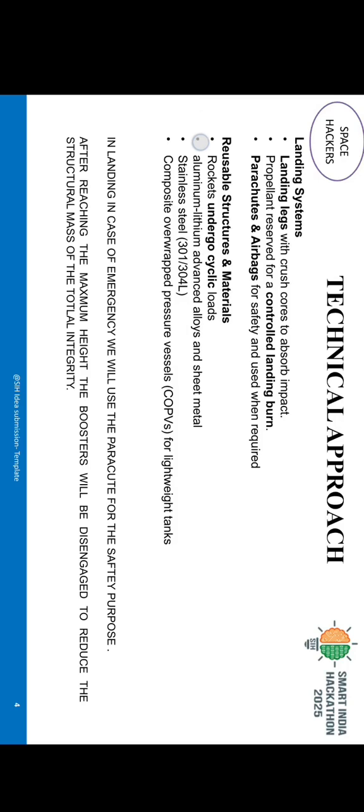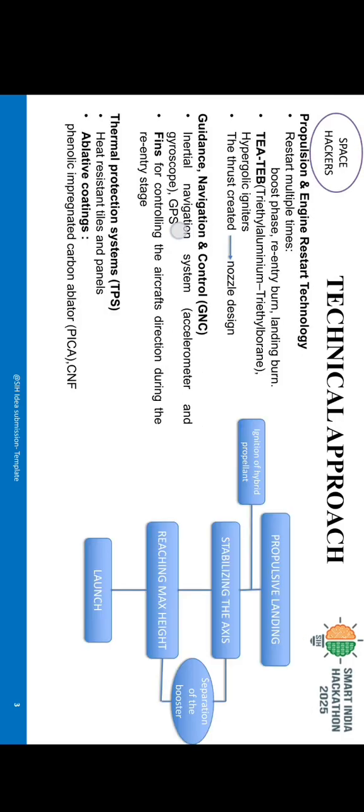In propulsive and engine restart technology, of course, the engine has to be started multiple times. For that, we have used TEA and TEB type igniters and hypergolic igniters. The thrust created depends directly upon the nozzle design. We have designed the nozzle accordingly to create a high thrust based on the area ratio and the pressure configurations.